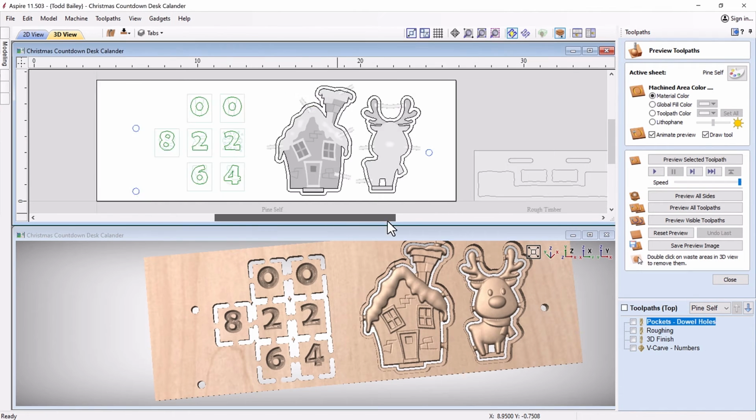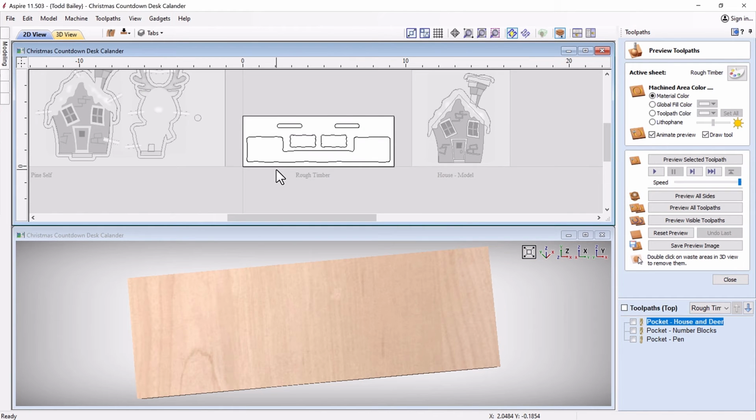Now let's go ahead and have a look at the base here. This is simply made up from a bunch of pocket cuts. Now, I actually have a piece of wood that's exactly the right size that I want. So I'm going to have to use an interesting way to fixture this to my wasteboard. So I'm going to put down a long piece of wood. Then I'm going to double-sided tape this piece of material right up snug to it. And I'm going to put a second piece of wood to make sure it's clamped on its x-axis so that it won't slide around. The tape will hold it in place and it won't move. And that way I can use this exact side. I'm going to zero off the corner of this so that everything will be lined up nicely.